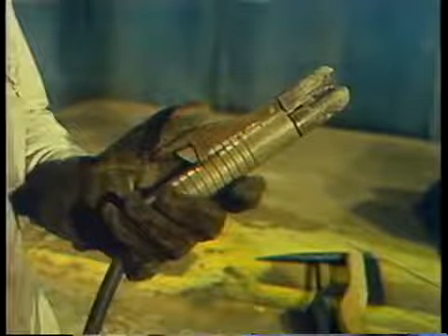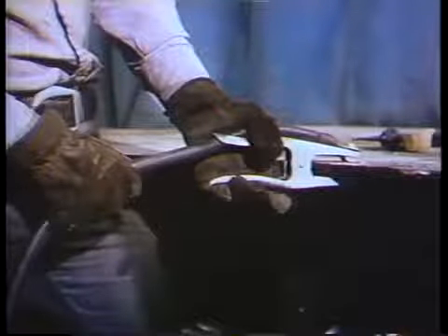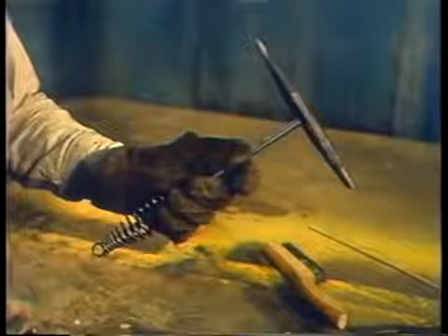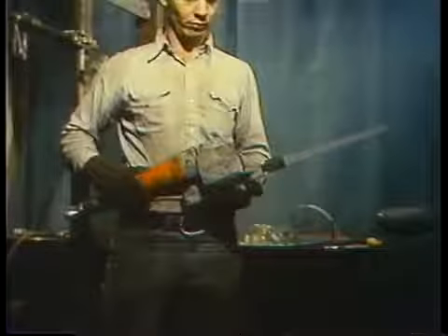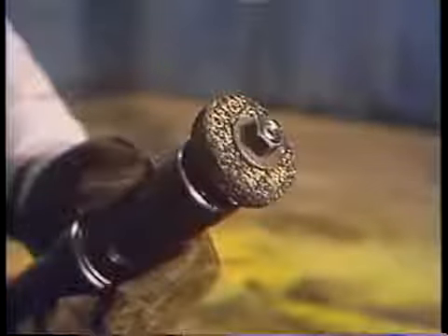Before starting the job, get all of the equipment you'll need to do the work. First of all, you'll need a welding machine. If there's a written procedure, it may call for a particular type of welding machine. The tools that are needed include a rod holder, which is also called a stinger, a grounding cable, a slag hammer, a wire brush, a saw to cut the tubes, and a grinder. Before they're used, check the tools to ensure they're in good condition. For example, make sure that the welding cables are not frayed or broken.